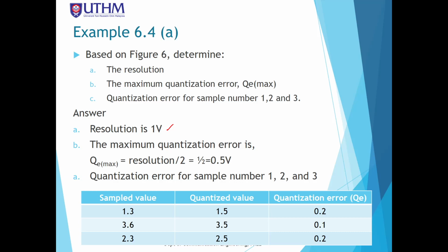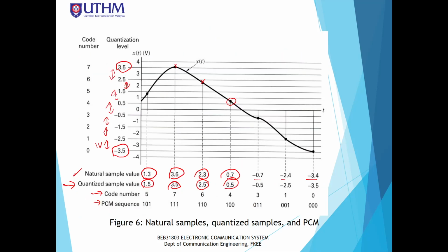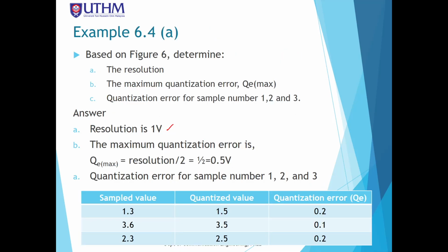Okay, and then what? The maximum quantization error, QE max. According to this equation, it is resolution divided by 2, or step size divided by 2.